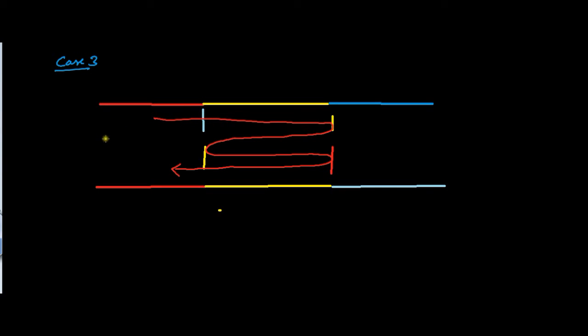This is source impedance Z0, this is Z1, and load impedance RL. So let's calculate the total partial reflection coefficient for this signal path. As we know, this is T1, and some part will be reflected back, given by partial reflection coefficient 3, and some part will be reflected here, given by partial reflection coefficient 2, and again partial reflection coefficient 3, and again this is given by T2.